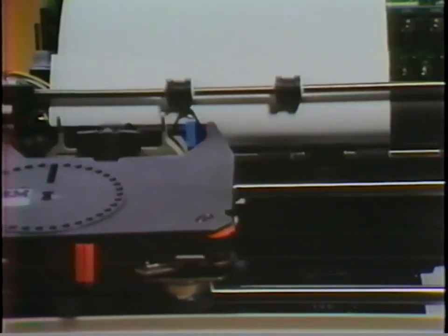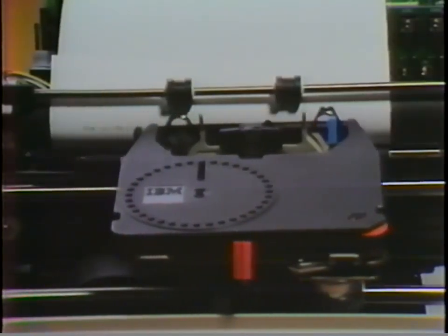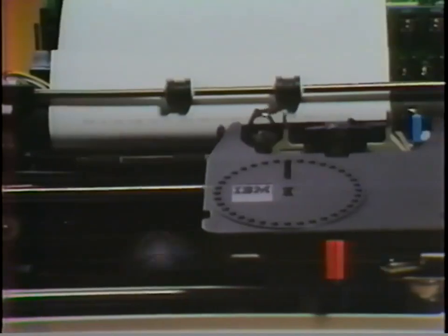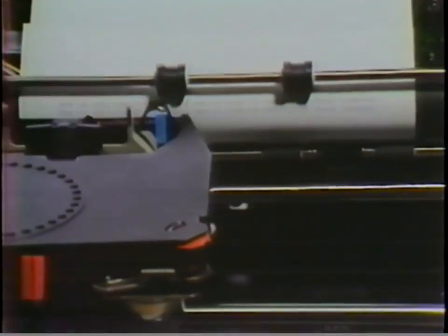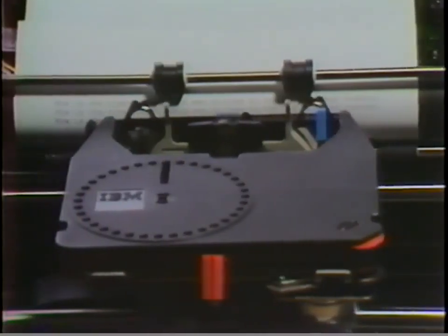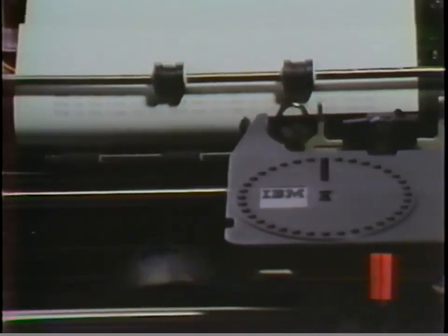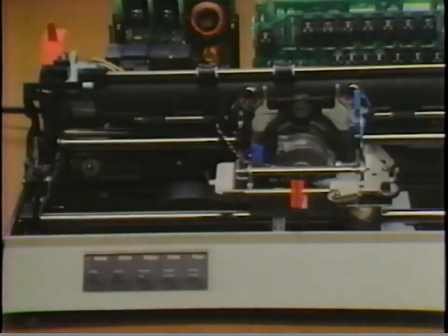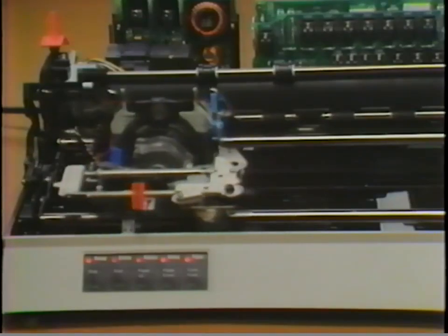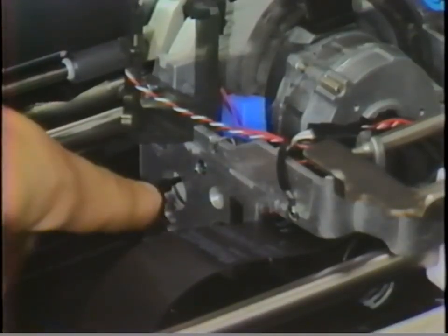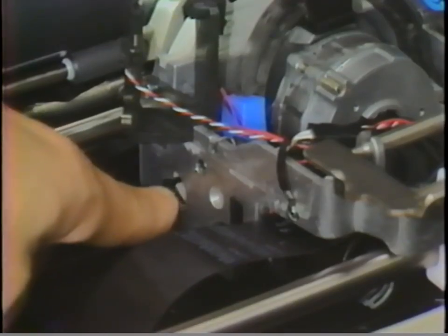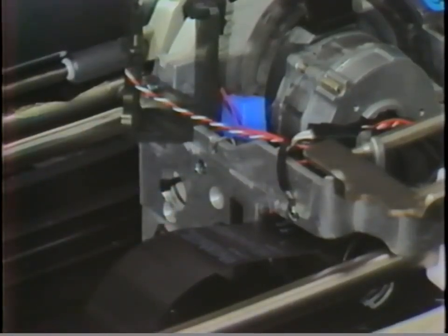The transport motor is responsible for all carrier movement, carrier return, tab, backspace, and escapement. The printer board determines how far to move the carrier and then drives the transport motor the correct amount dependent on the pitch of the print wheel. During POR, the transport motor moves the carrier to the left side frame, then back out to the left margin. The homing flag tells the printer board when the carrier reaches the left side frame.